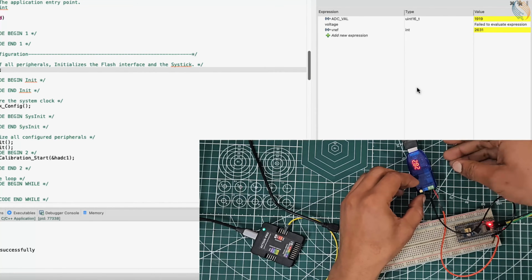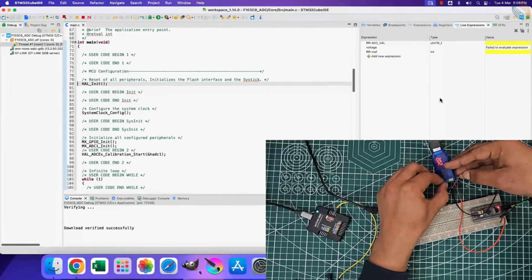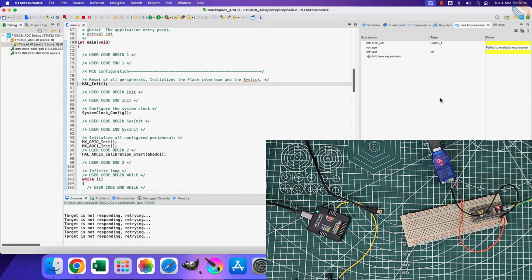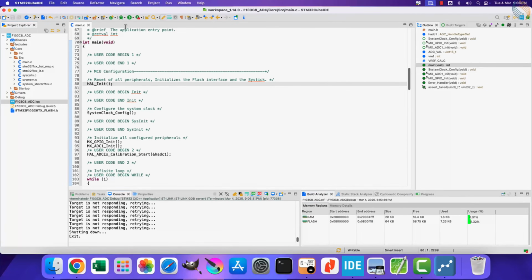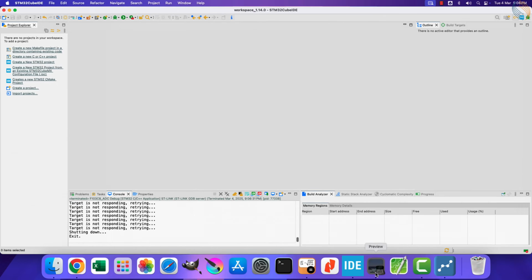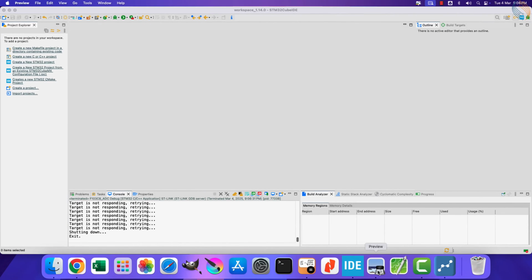When the battery voltage drops, the VDD will also drop, and so does the Vref. As long as the Vref is above 2 volts, things will work just fine. We can use this measured Vref to calculate the ADC input voltage. So we saw two MCUs so far. In both of them, the Vref pin was connected to the VDDA, which was then connected to the VDD. Hence we could not have separate reference and supply voltages.